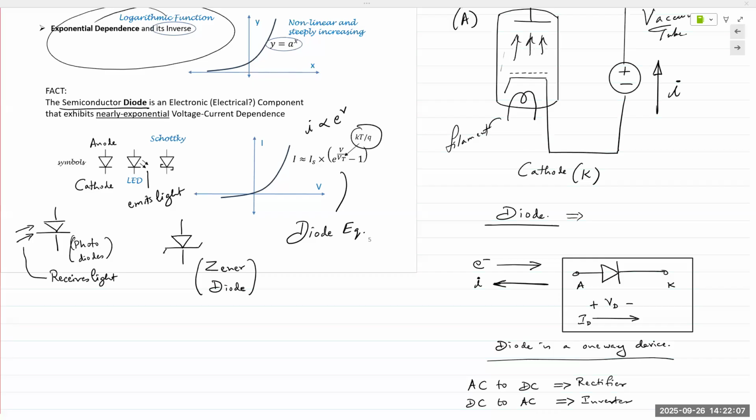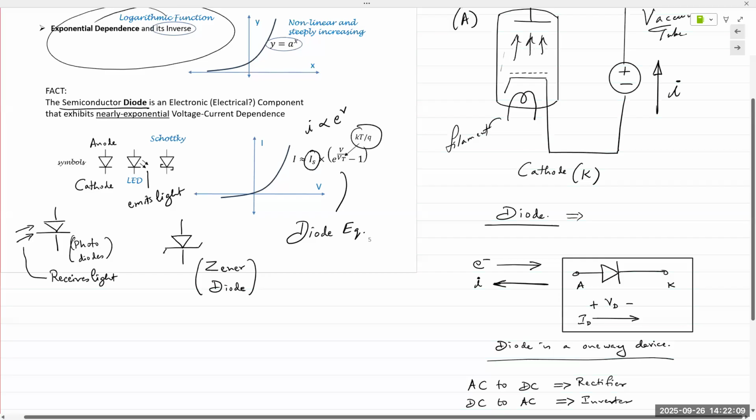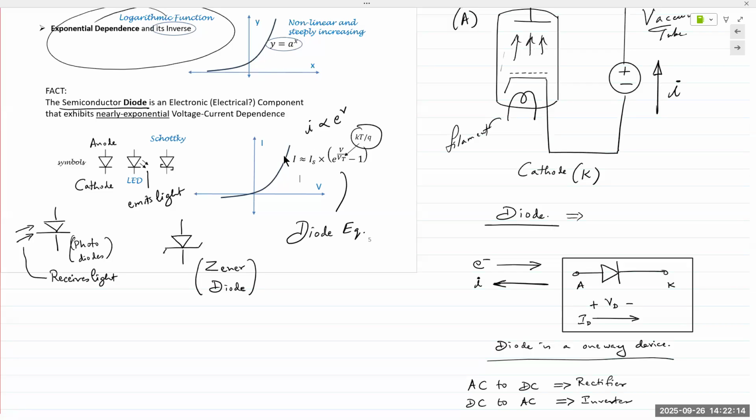That's a good question. What does the IS in the diode equation stand for? This IS stands for saturation current. Saturation current is a small amount of current that inherently flows through a diode, the semiconductor material. And again, I will not brush it off, but technically that would be part of semiconductor device physics, 315, which we learn in semiconductor devices at 3 o'clock. You're welcome to attend any of those lectures if you want, right here in this classroom.